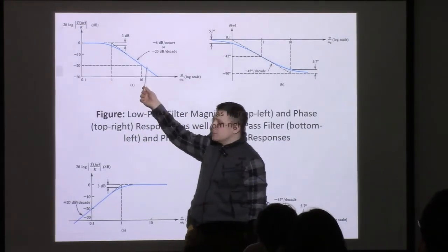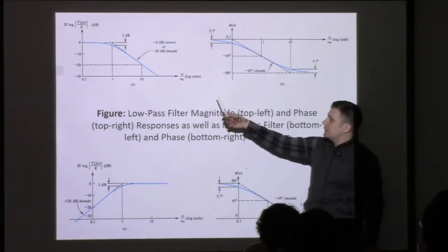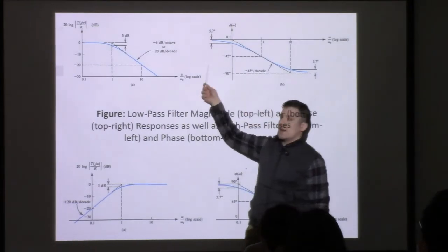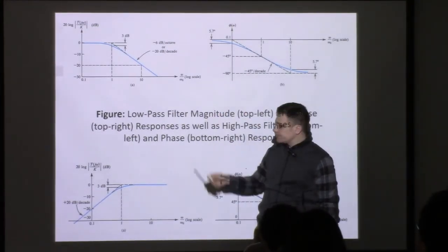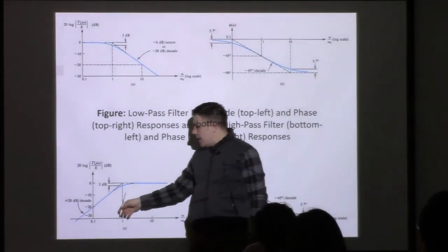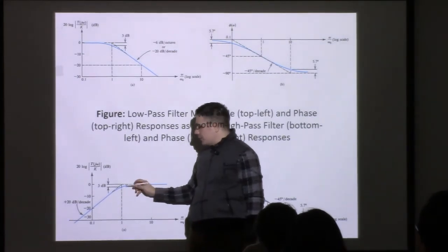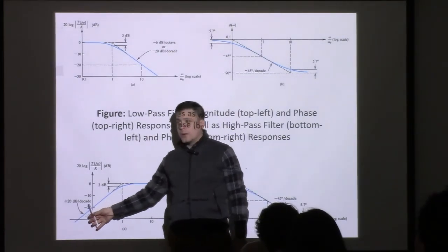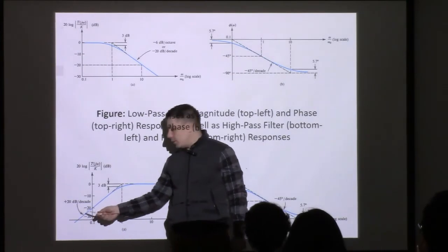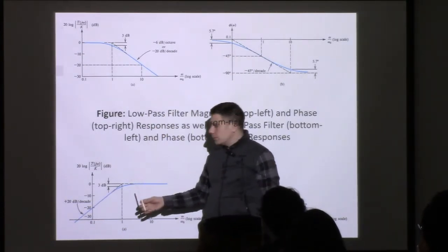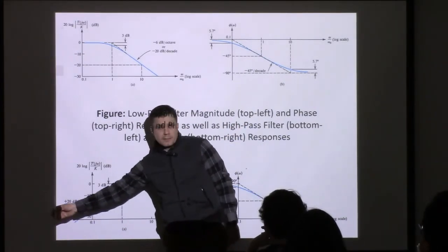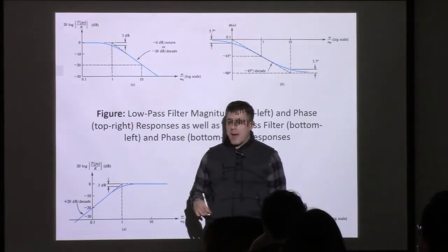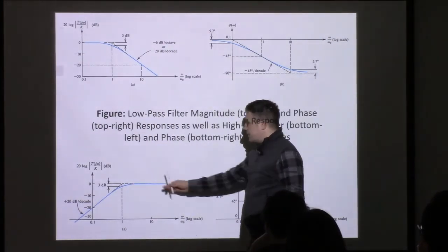And every dotted line would be, so that's 10 times, 100 times, 1,000 times, etc. So over here at the cutoff frequency, we have the inflection point. It continues downward at negative 20 decibels per decade, or positive, I guess, because it's going upward, all the way back. And then it stays flat.